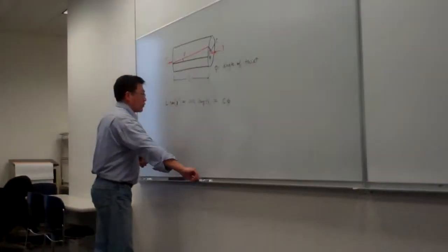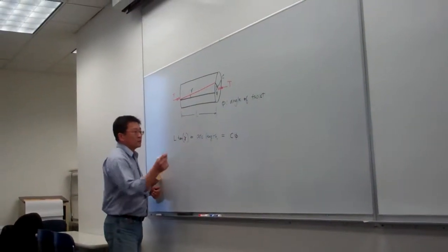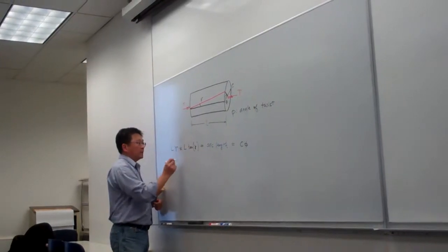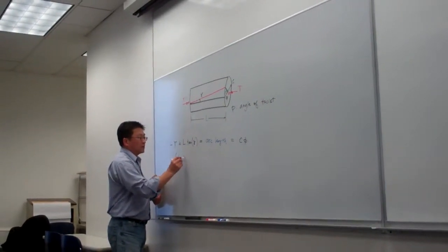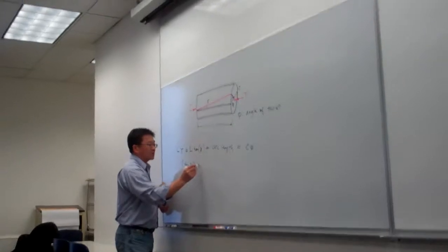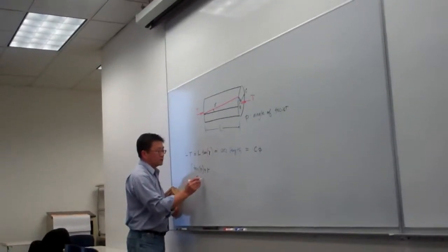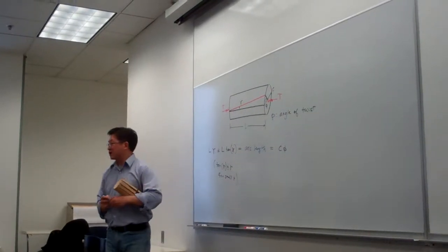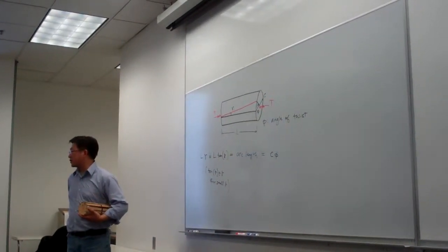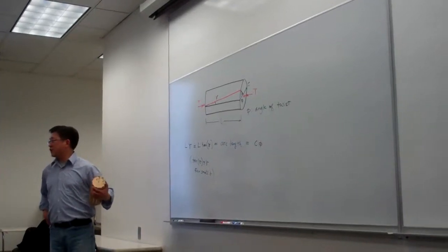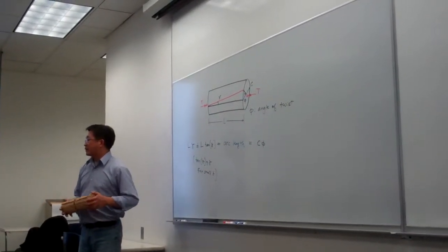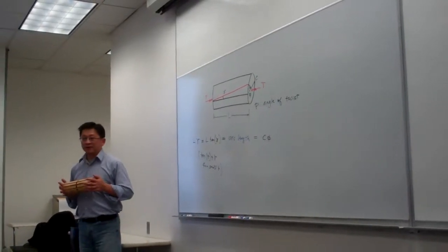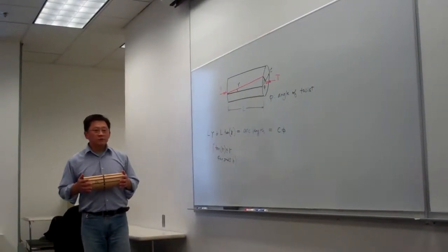So in practice this is so small that it can be approximated simply by L times gamma, because for small gamma we simply take these approximations. These approximations can be very accurate for most solid mechanics models because the Young's modulus is so big.